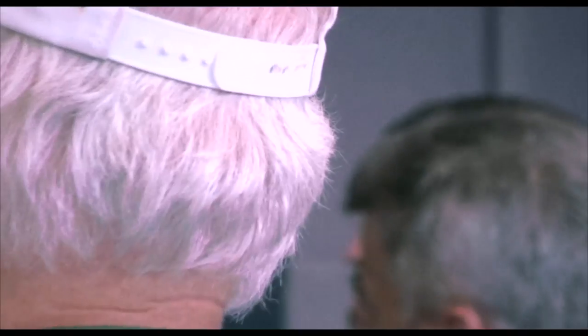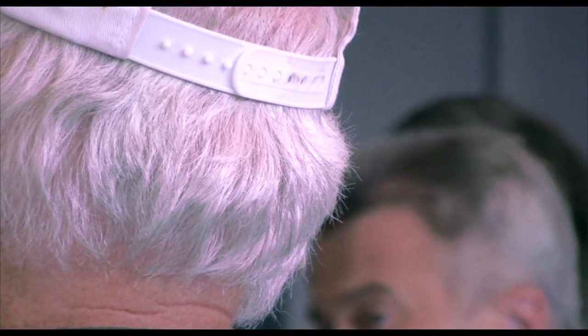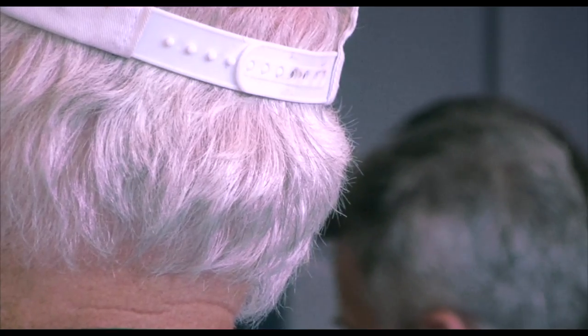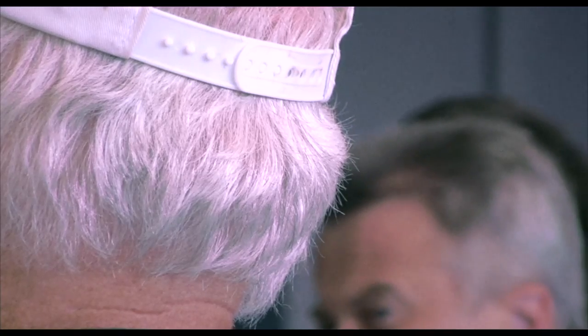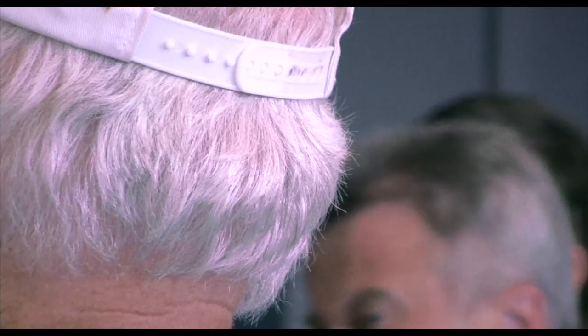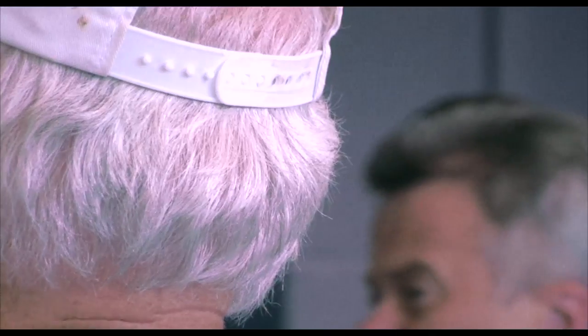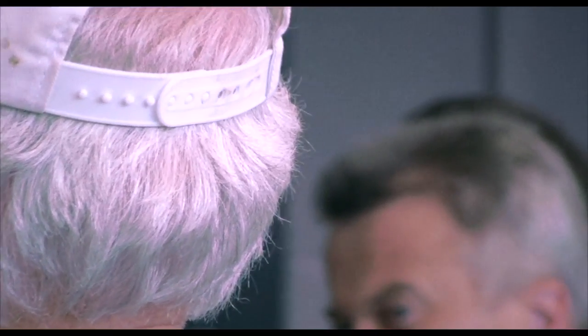Did you use a leading edge slat instead? Instead of the double slotted flap, did you use a leading edge slat? You know what? I didn't address slats because when you're using natural laminar flow, the slats tend to kill it. If they retract very cleanly, it would work. Yeah, you need a clean leading edge. It's a mechanical problem, just to get it really clean would be the problem. It'd be a tough one to solve.